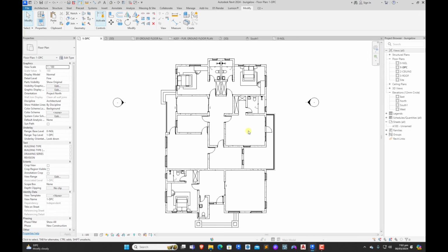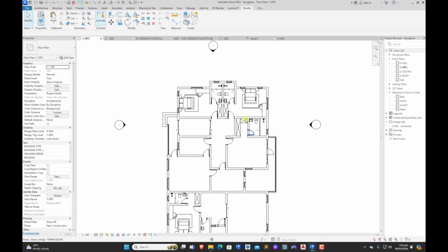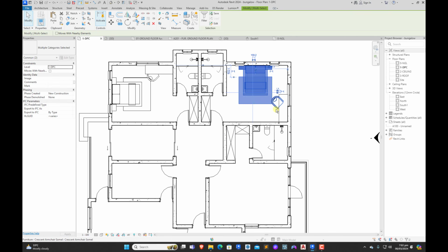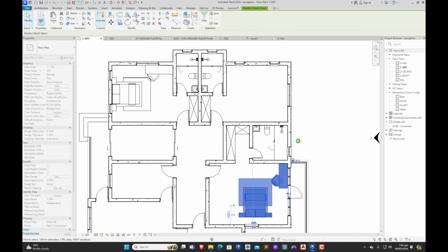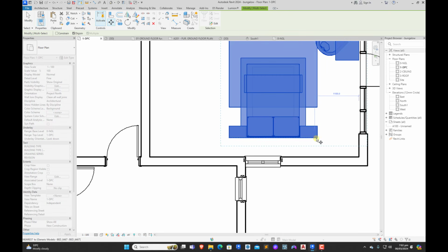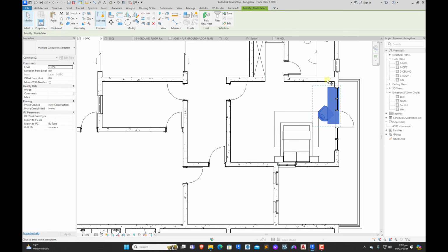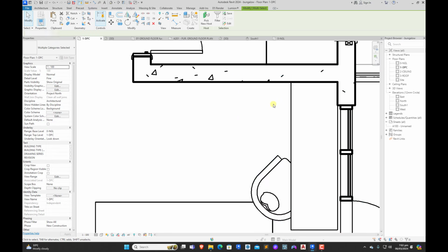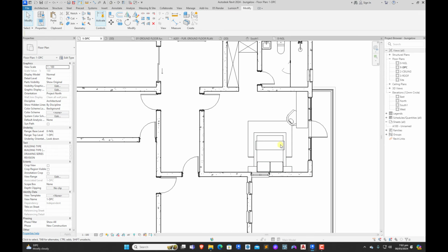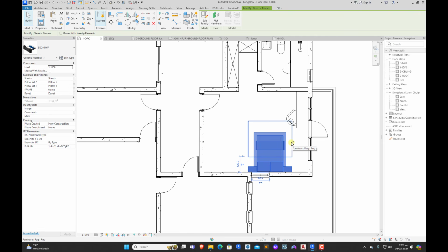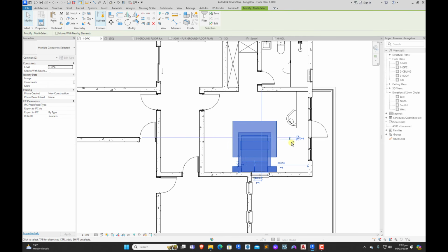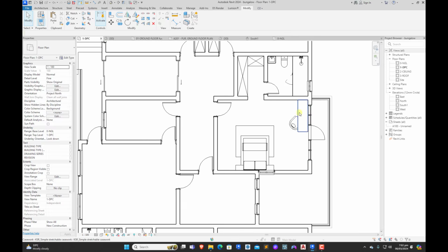Now it's remaining the master's bedroom. Now for us to furnish the master's bedroom, the same thing, we select the components we need. Okay, now we're going to mirror this way. Alright, we bring this to this point, make sure it fits perfectly. Here, we adjust it a little bit. Then these two, select them, then we align them to this point. Then we align them to this point.